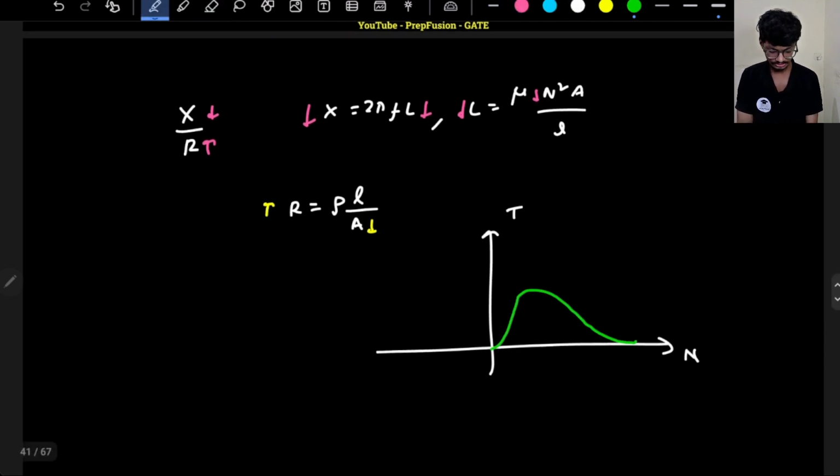Okay, this is the torque that we get. Now what we'll do: this is the torque due to the main winding, right? Now the auxiliary winding is also there at starting. So the auxiliary winding will provide an additional torque. Due to the auxiliary winding, it will have some starting torque, and this will get added with the main winding torque.